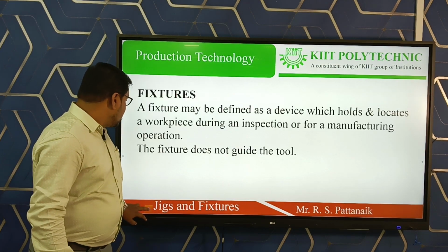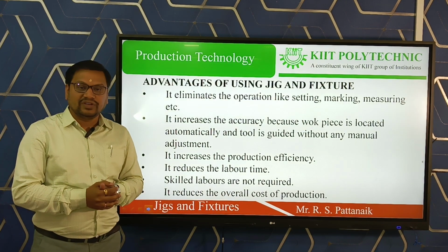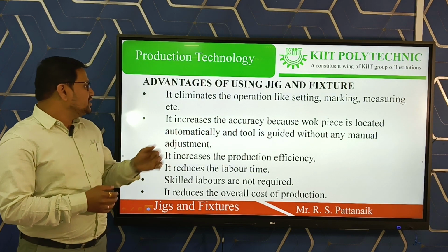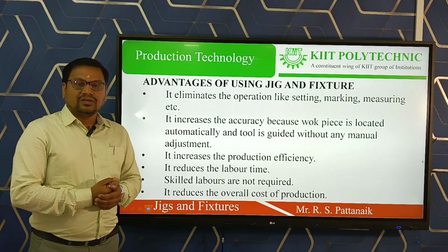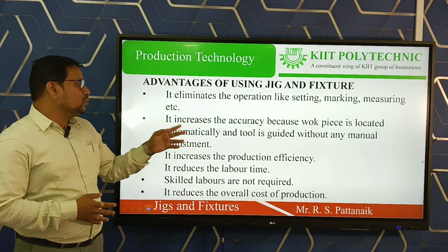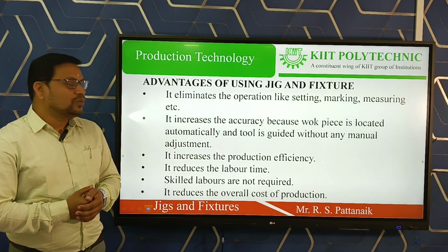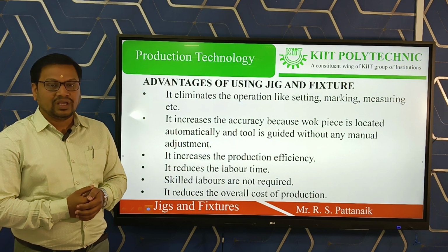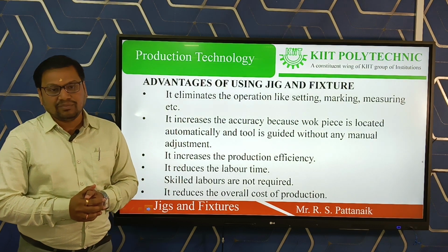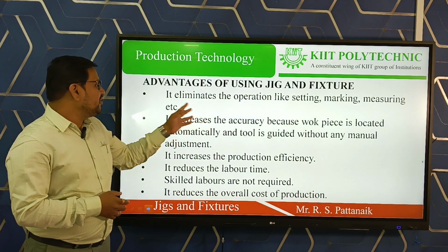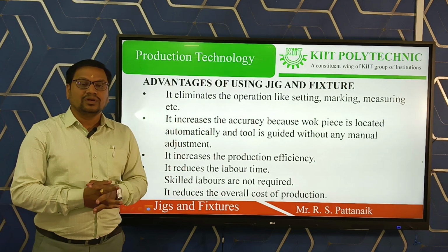Next are the advantages of using jigs and fixtures. As we already discussed, the workpiece is located automatically and the cutting tool is guided without any manual adjustment. So it eliminates operations like setting, marking and measuring, and it increases the accuracy of the workpiece.